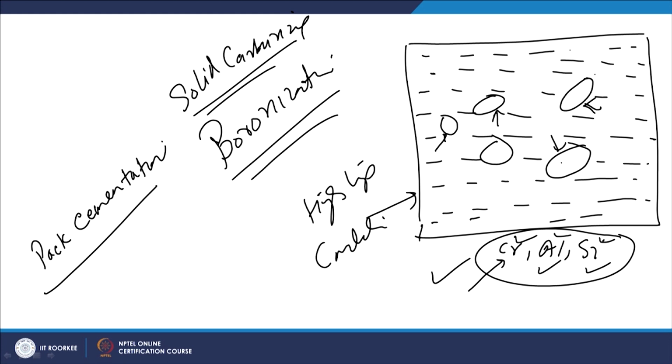In that box we also put the components whose surface is to be modified, and then the entire chamber is kept at a high temperature for some time, so that the diffusion of such elements at the surface and near surface layers can be facilitated to modify the surface composition so as to achieve the enhancement in surface properties.